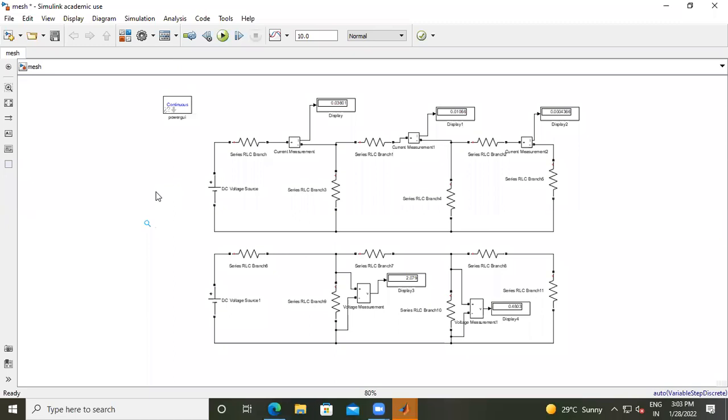Similarly, branch B is connected between 2 and 4, and is directed towards 4. So node 4 will be minus 1, node 2 will be plus 1. What do you call that? Fundamental incidence matrix. Is that okay?